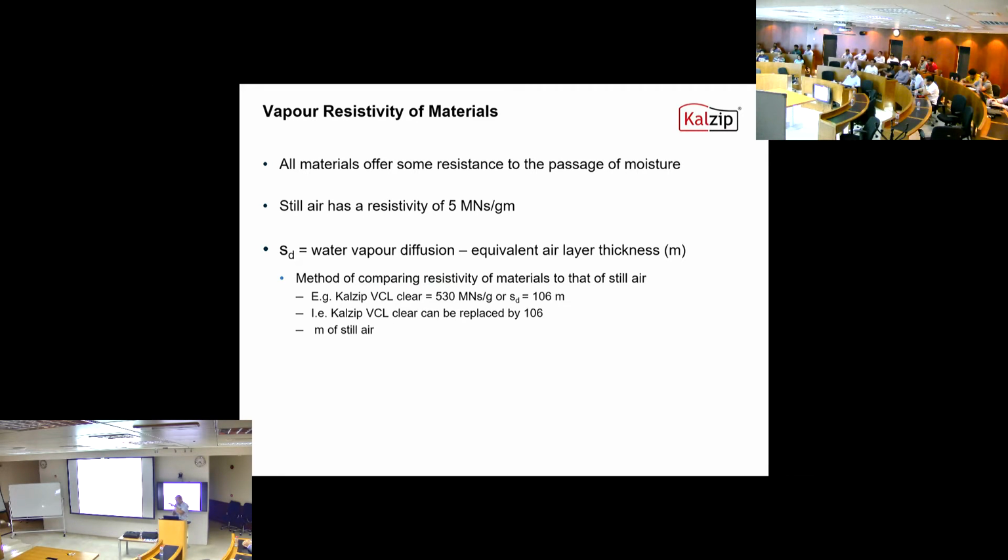As the VCL comes down and goes into the gutter, on the sharp edge where it could get torn, you could put a metal flashing in, like a closer flashing, to hold it in place so it's not exposed to that edge. So you put a closer flashing in, which sits on top of the liner, and just protects that edge of the VCL so it doesn't get torn. That's one way of protecting it from getting torn.